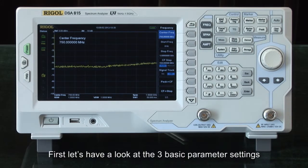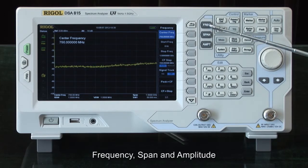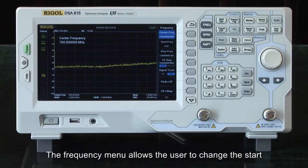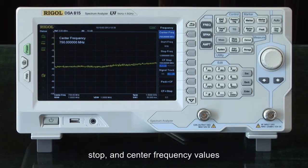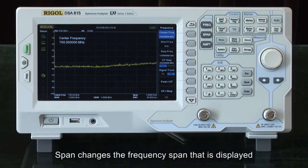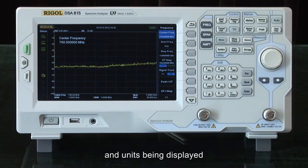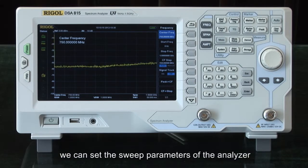First, let's have a look at the 3 basic parameter settings of frequency, span, and amplitude. The frequency menu allows the user to change the start, stop, and center frequency values, as well as other frequency-dependent settings. Span changes the frequency span that is displayed, and amplitude allows the user to change the vertical scale and units being displayed. In the sweep control area, we can set the sweep parameters of the analyzer.